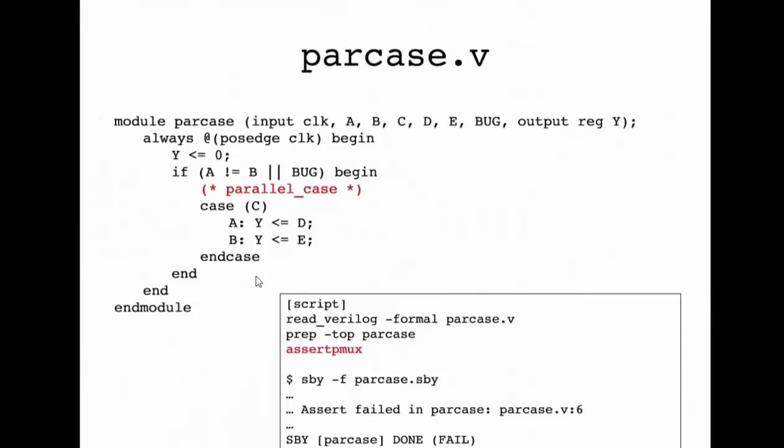And with the parallel case statement, the circuit designer tells the synthesis tool that only one of those values here will equal the condition variables. And of course, a synthesis tool is free to use this and optimize on that. But there is no guarantee that the synthesis tool will do that.